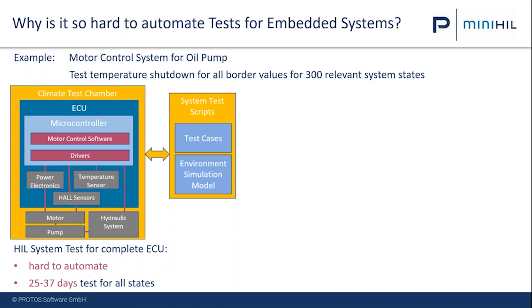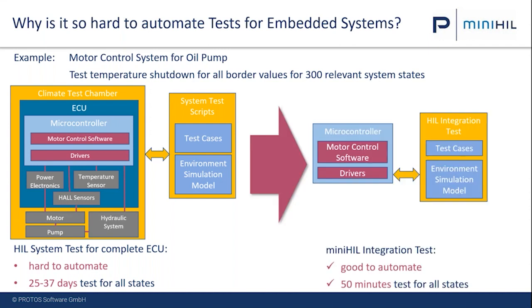It never actually happened. So what we did is we just focused on the microcontroller with the motor control software and the driver. So the complete software stack on the microcontroller. And we simulated the complete environment, including all the motors, all the sensors, and so on and so on. It's not as hard as it sounds to do, but once you have a simulation in place for the complete environment, you can bring the system in any state you want. So by doing that, you can make a failure injection and so on and so on.